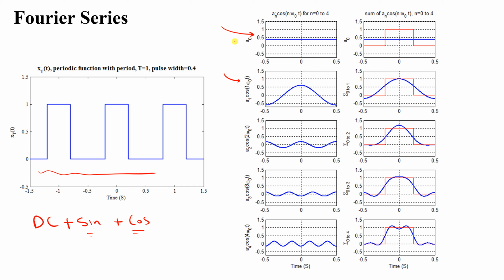So we have a DC plus fundamental component, and we will have this signal. Now let's say we found the second frequency component, double omega. You'll find it is like this using Fourier series. Now add these three together, and you will get this shape, which you can see is becoming closer and closer to our final shape. Now let's say we found the triple harmonic. It is like this. If I add all of this, we will have this shape.